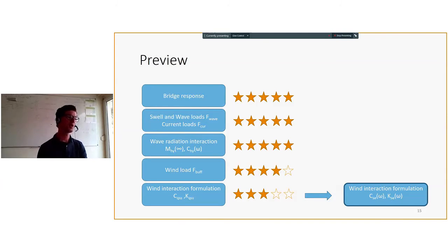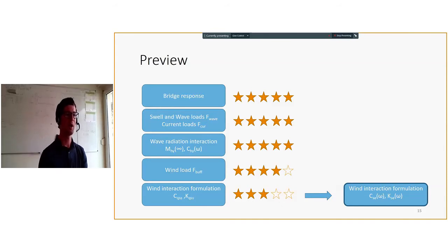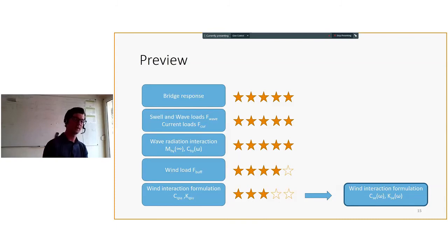But here on the wind load side, I'm more familiar with the theory. I can comment that what we implemented is very good. The quasi-steady theory of wind buffeting load is sufficient for producing the response. However, we didn't include, for example, admittance functions, and those could be important. They could reduce the effect of buffeting, and that means a cheaper design. So if I were an investor, I would invest in this area.